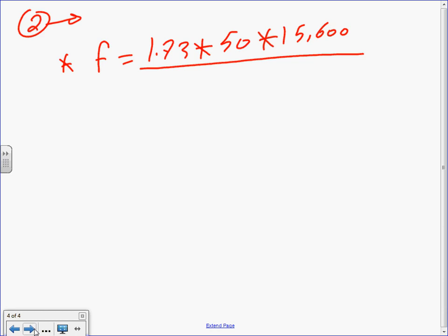Everybody understand? We typically pull, Andrew, my friend, what? Conductors or cables? What do we pull, Andrew? What do we typically pull for feeders? We pull cables inside conduits or conductors? Single conductors, right? We pull single conductors inside the conduit.